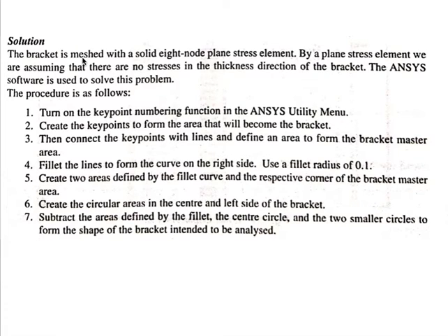The bracket is meshed with the solid 8 node plane stress element. By a plane stress element, we are assuming that there are no stresses in the thickness direction of the bracket. So this is one constraint or degree of freedom we have taken, and thus ANSYS software is used to solve this problem. So we need to follow this procedure.